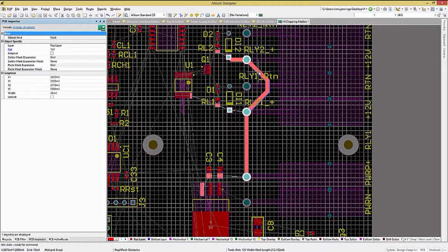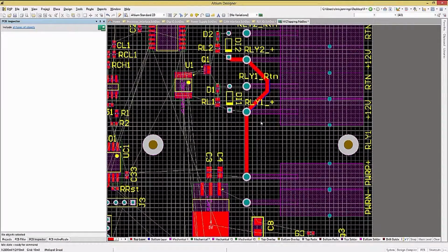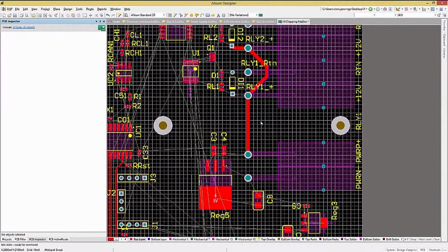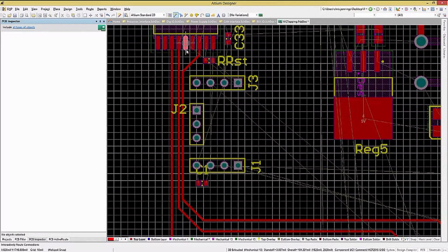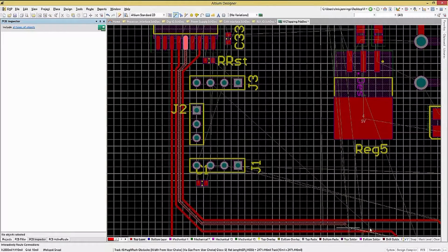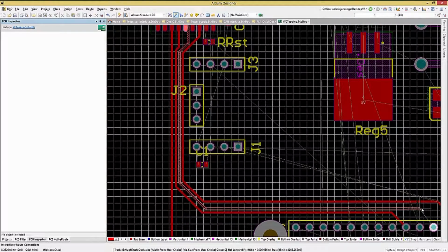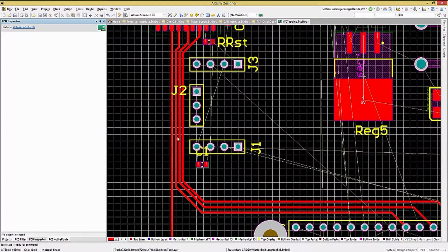During the process of routing a design, a typical situation arises due to multiple tracks already having been routed. These block adding an additional track. Altium Designer allows for routing in between existing tracks in the push and shove mode. Adding a new track will cause the existing ones to move and make room. Note there are limitations to this, one in fact being the PCB rules are still enforced. If adding a track breaks a clearance rule, then the routing will not be enabled. Again, be aware that the rules will always be enforced.